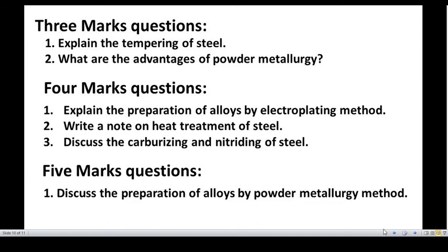Next, let us see what is nitriding. Nitriding is also a heat treatment process that diffuses nitrogen into the surface of a metal to create a case hardened surface. That means only the surface becomes hardened but the core remains soft. In nitriding, the diffusion of nitrogen takes place at relatively low temperatures, near 524 degrees centigrade.